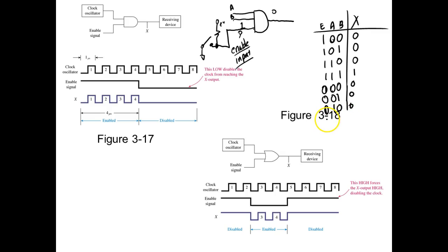This would be a 0. And that would be a 0. Well, if the gate was enabled, then when I put that all on there, that output right there should have been a 1. So no matter when I put a 0 on my enable input, my output would always be a 0.